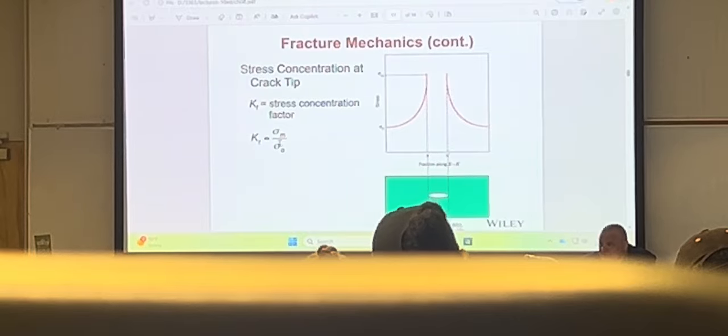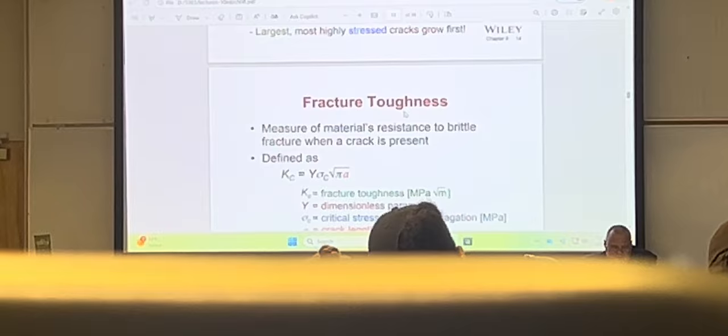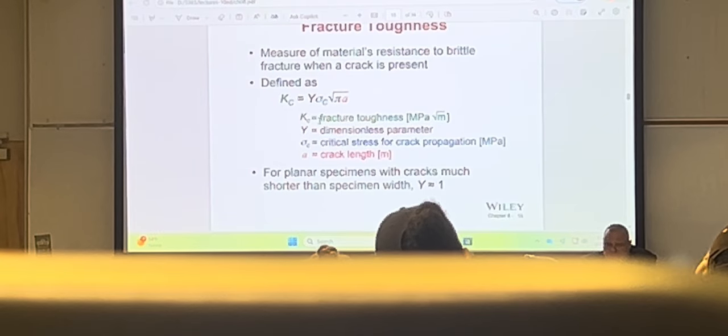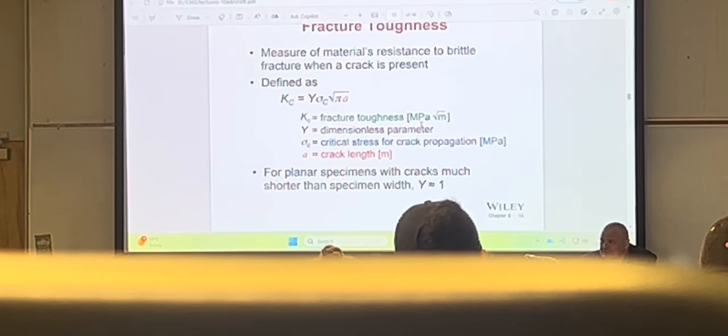It's the ratio of the maximum stress to the remotely applied stress. And Kc is the critical fracture toughness, which has the units of megapascal square root of a meter. I mean, we did everything to confuse the public and the students by using the same letter.